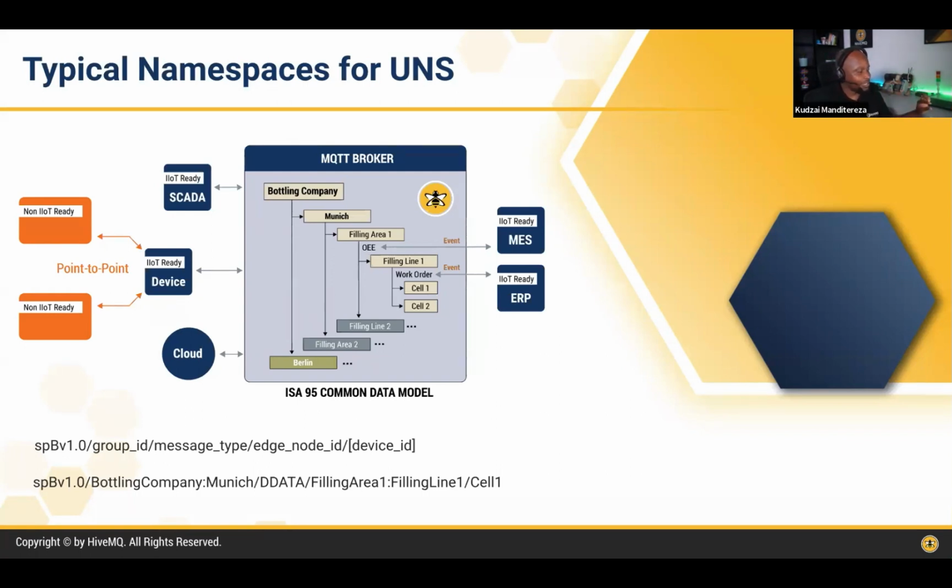So that is the MQTT topic representation that Sparkplug specifies. It's not enough to stitch together the different levels of your hierarchy. So another option is to use delimiters to pack all of that information into that topic representation, and then be able to unpack it whenever you consume this information. So if you need to use Sparkplug, this is how you currently do it.